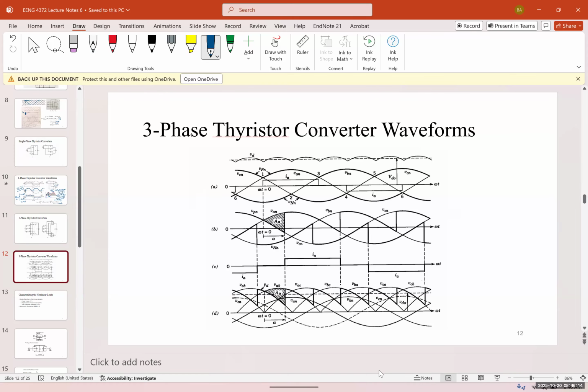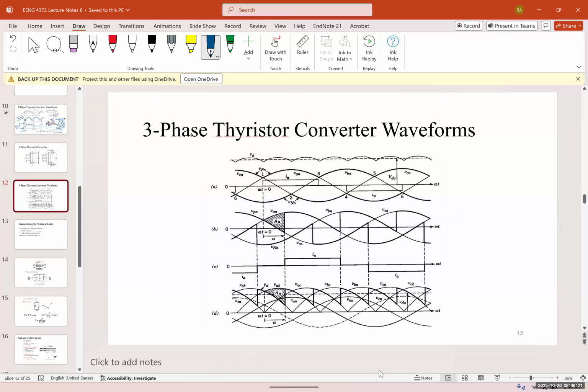As soon as the voltage reaches 0.7 volts, it turns on. For a thyristor, you can control it. And the equation is going to be much more complicated than the one phase. I just wanted you to learn about the waveform and how the waveform works actually. And again, you have an alpha, that's the degree that you initiate and trigger the thyristor.